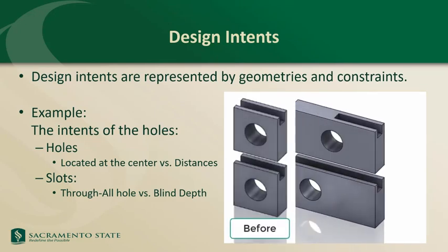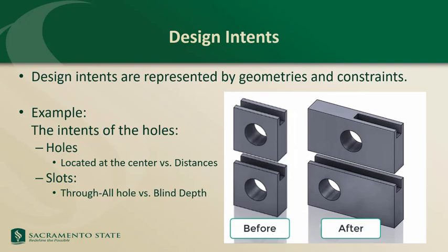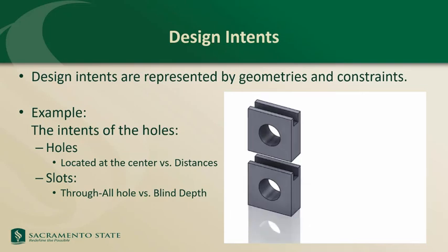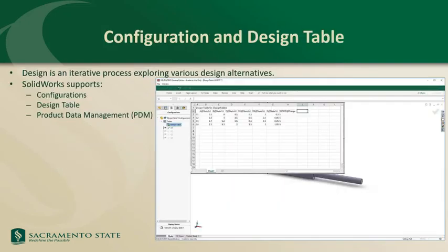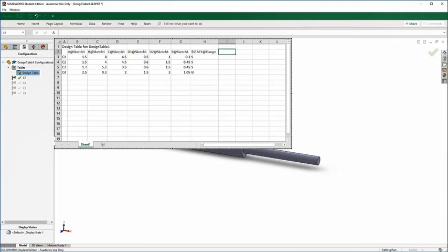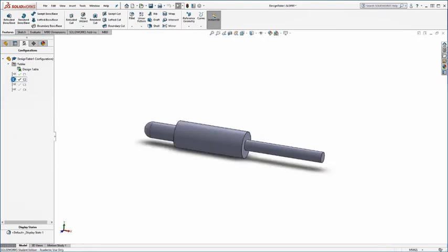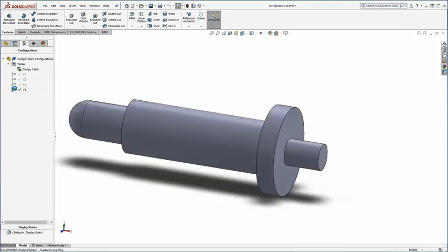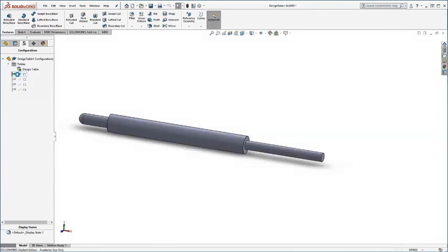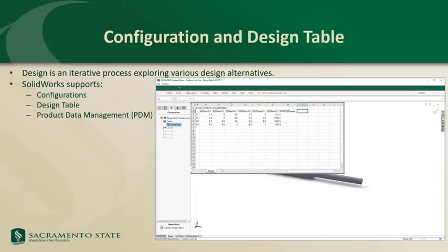The product design is an iterative process. The model will constantly change, but the model should maintain important design intents. CAD is a design tool, and it should be able to represent many what-if scenarios. Even for one part, designers may want to make various versions of shapes. If a separate file needs to be created for each different variation, maintaining so many files will be a nightmare. In SolidWorks, each document can have many different configurations, and it can be created and managed by a design table.